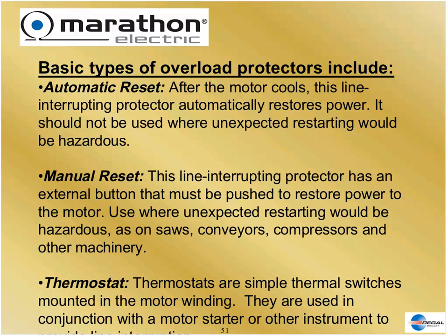Another typical example in your home would be your garbage disposal. You put a rag or a spoon down the garbage disposal, it overheats, it overcurrents, and it trips this button. This button is usually located underneath the sink, way in the bottom of the unit. So you have to physically go down, get your hands away from the garbage disposal, and go down there and start pushing on this button to get it to reset. The concept is your arms are not long enough to still dig in there to try to find the rag when you're trying to press on this button if you forget to turn it off. Otherwise, you may cut your hands off.